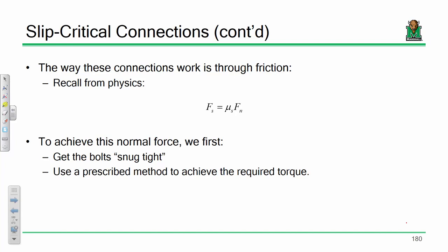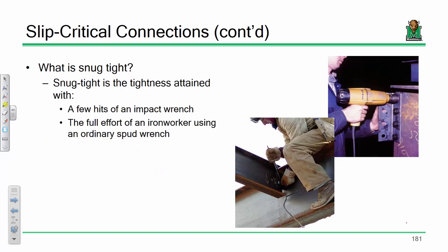And then once you get the bolts snug tight, you then need to use a prescribed method in order to achieve the required torque. And there's a number of different ways to do that. But first off, it's a common question that students ask, what's snug tight?